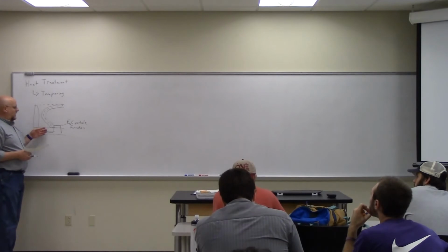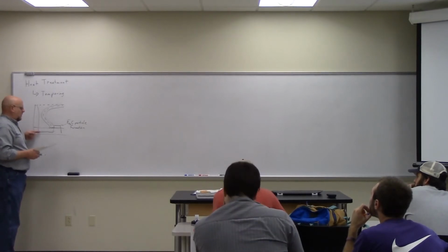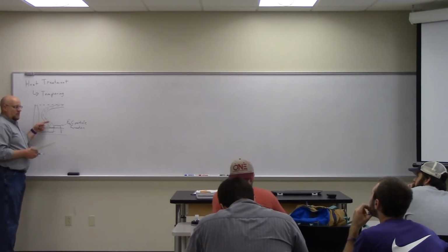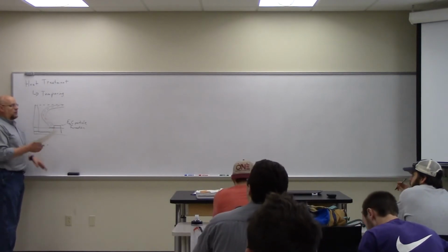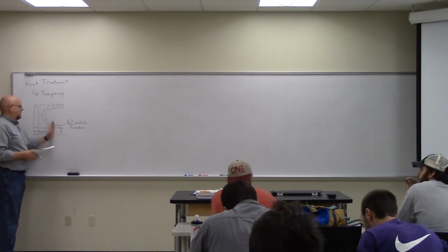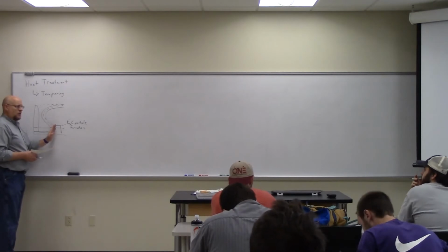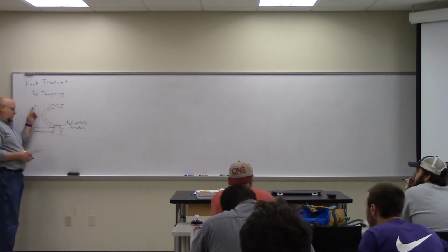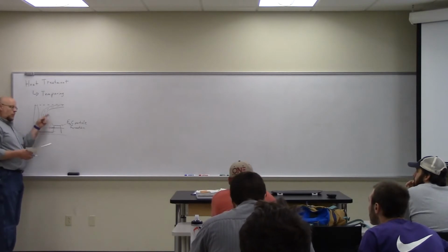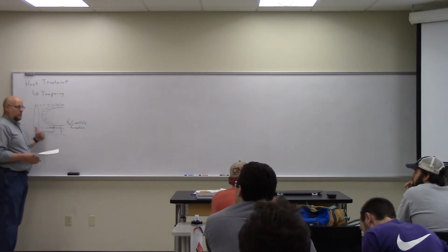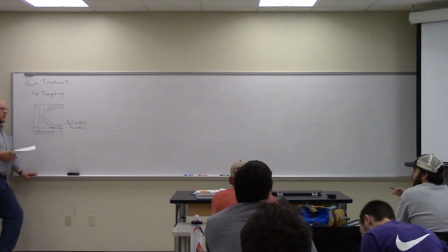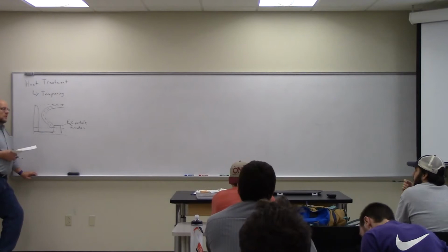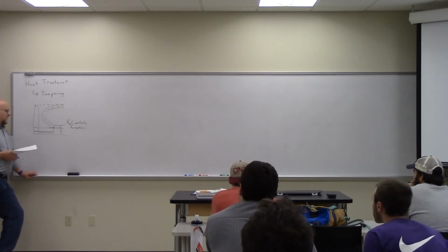The point is, once you've quenched it down here, you can raise it back up again. Once you're down here, you've undergone the transformation, so raising it back up here or there doesn't matter. This time frame here is sort of like an hour-ish. Usually you quench it down, you do a bunch of parts, then you come back and warm them up to temper them. You don't do it immediately. And that goes with saying that the material properties only apply when you're cooling into them. If you're going back up, the 1%, 50% doesn't have any meaning.